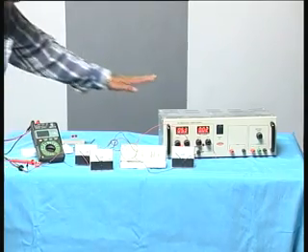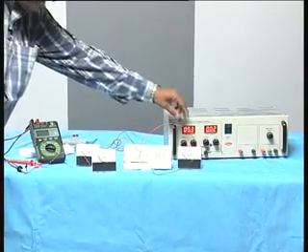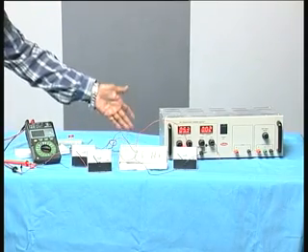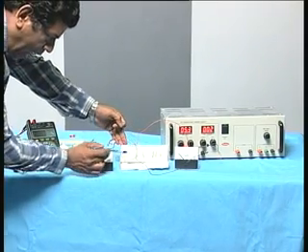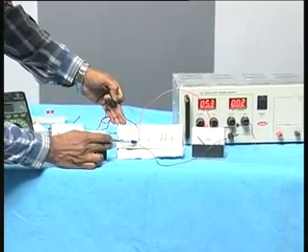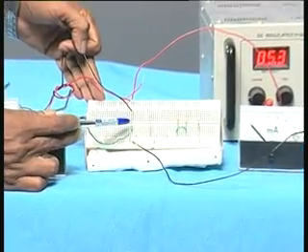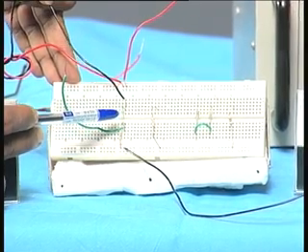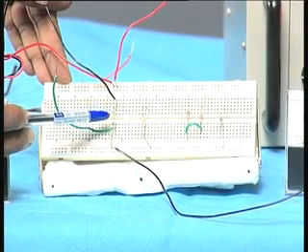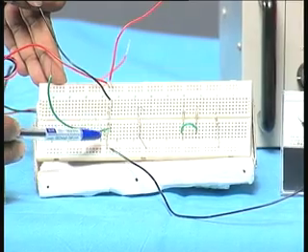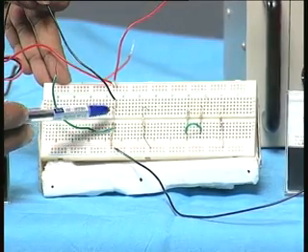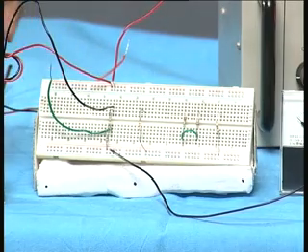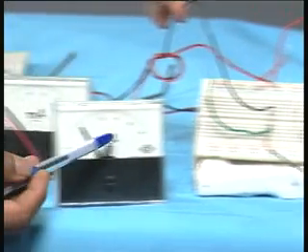Here I have a power supply, and the two wires from the power supply are connected to a breadboard, which we have already seen, and you can see I have connected two resistors here. Each one of them is 1000 ohms. Some of you are familiar with the color code, which I already mentioned. You can see that it is brown, black, red and gold. Here again brown, black, red, gold. Therefore, these are 1K resistors connected, and the power supply comes here,